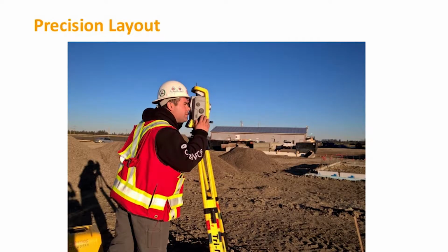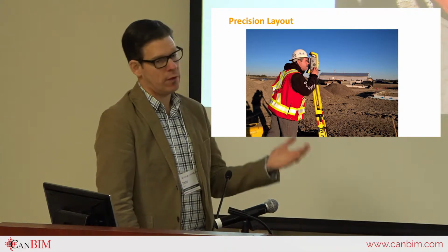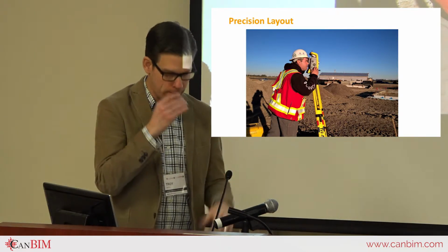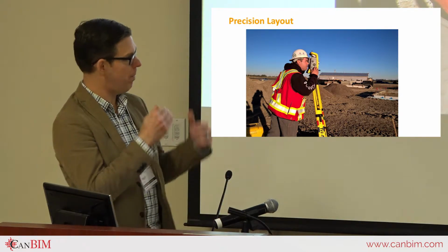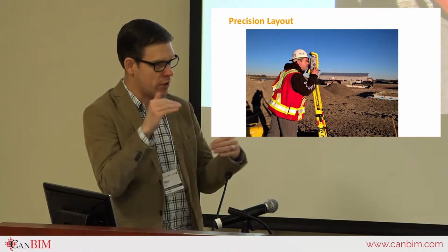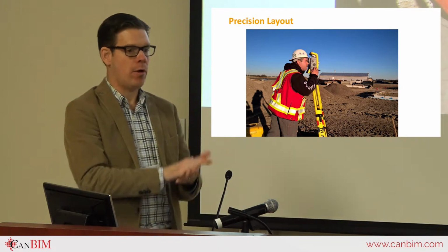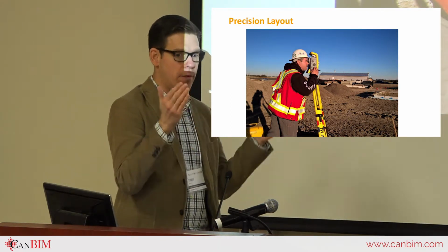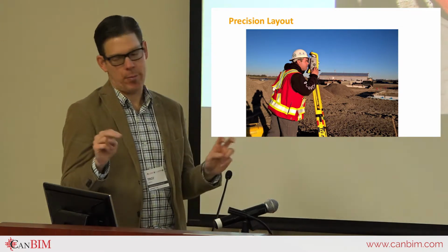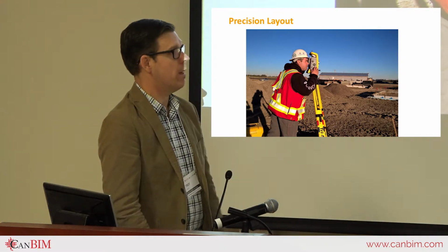So here's my as-built precision layout. We had one guy who was basically on site every day, and he was surveying the building as it was going up. And we would literally update the model based upon the points that he gave as the building was changing and the building was moving. So that the model, when it was all said and done, the as-built model was an as-built of what was actually built, not just a quasi-representation of what was actually built. So that whole process, I think, was really amazing.